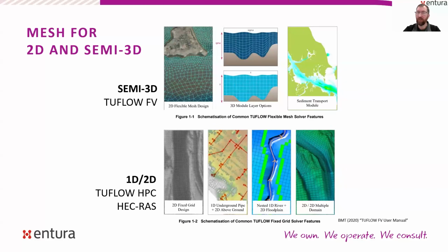And as one of the questions Craig mentioned, it's a whole new language with CFD. Well, that's true in some regards, but it's still talking about momentum. It's still talking about continuity equations, and it's a different numerical system. So the difference in going from a 2D model, or a semi-3D model where we've got the shallow water assumptions with hydrostatic pressure, is that with the 3D model we're able to solve pressure as an independent variable. That opens up the opportunity of water moving in vertical directions with vertical momentum, which is not something that the other models have.